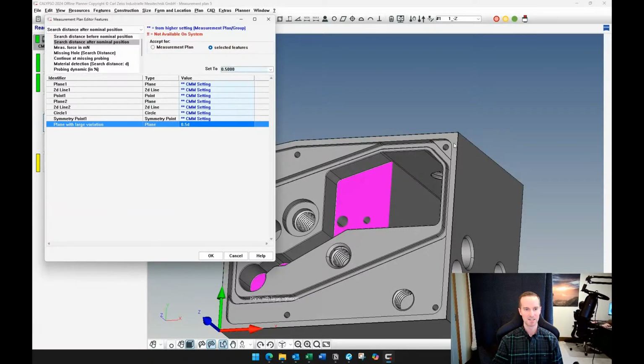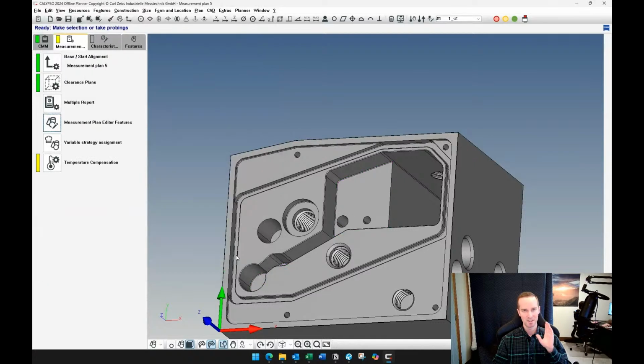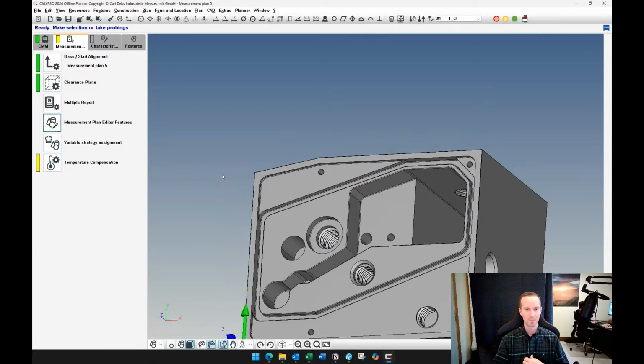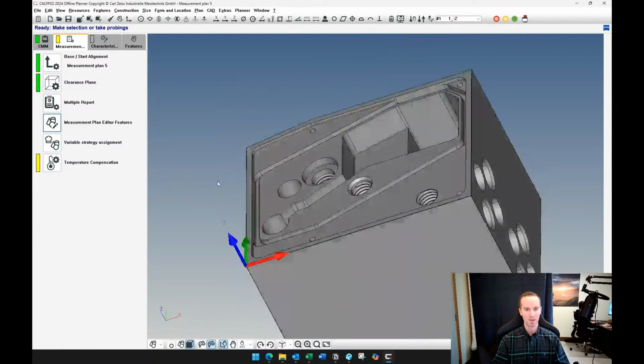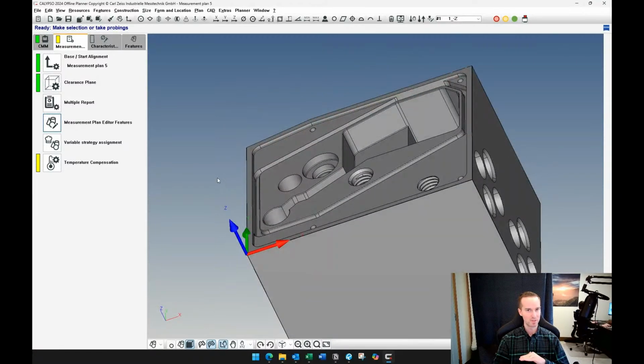Awesome question. So clearance and retract distance, it's always confusing to new people, and it's because of the naming. Because when you're thinking of clearance, you're thinking of the distance away from the surface, and same thing with retract. So they seem like the same thing. But what's going on here is you can have your entire program with a clearance distance of 0 and it will run fine, because the retract distance will be used as the first clearance before the first point.